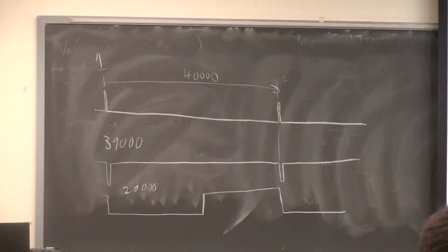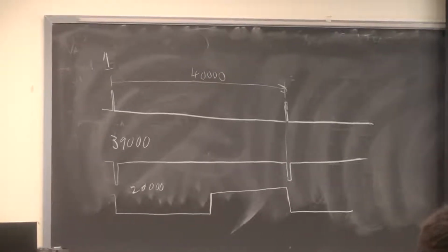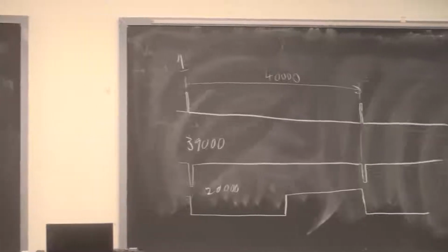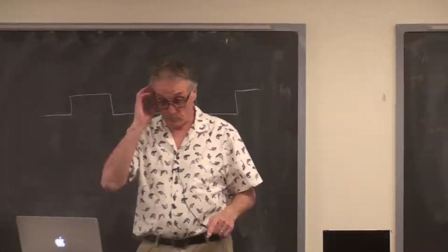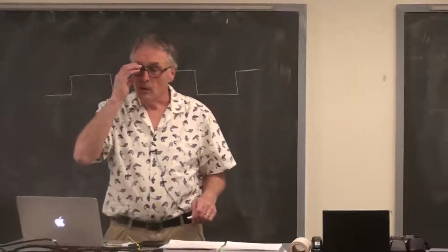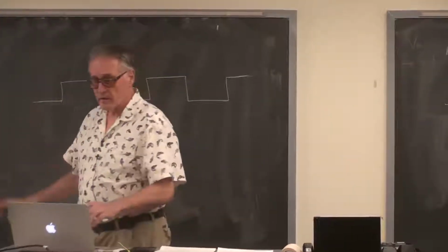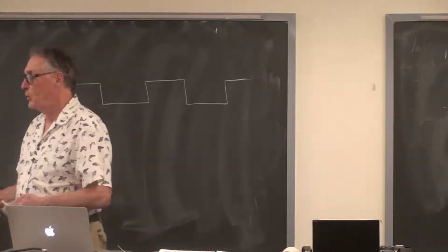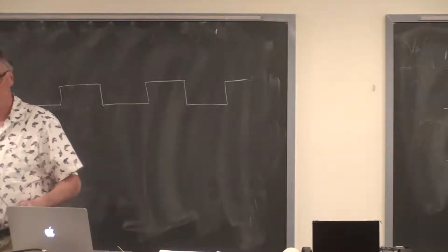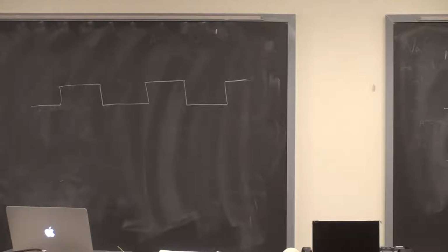So this is going to be the output that you feed through a resistor and into the opto-isolator LED. You need to do 3 things. You need to, of course, have a timer running. You need to open an output compare unit, and you need to set the PWM on time.